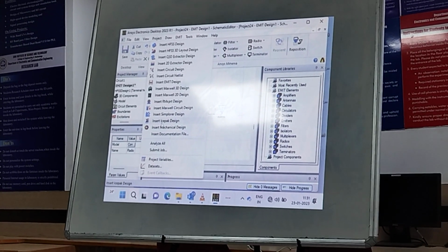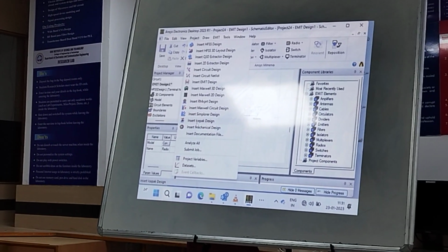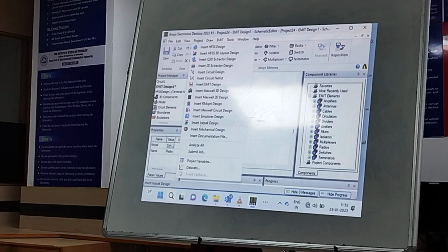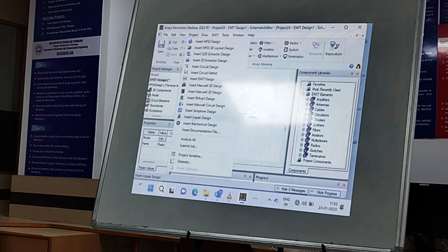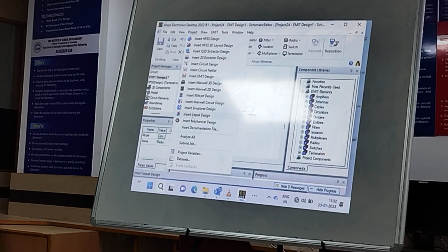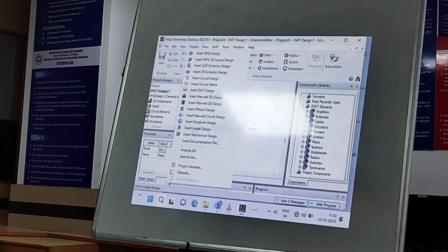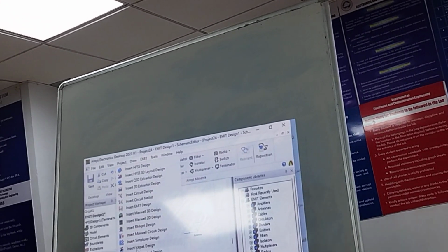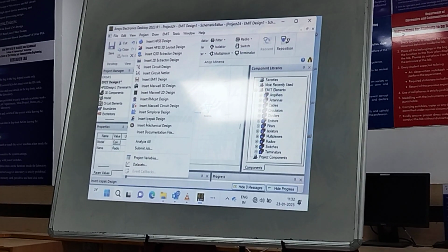And the boundary conditions, how we give it, like let's suppose in HFSS we will be giving a radiation boundary condition, or kind of PML layers we will be giving there. Okay, so instead of that kind of boundary condition, we will be giving a temperature dependent boundary condition here. Like at a particular wall, what will be the temperature, and it will be basically an external environment, how it will be, that we will be representing there, and based on that our electromagnetic signal losses will be converted into heat effect there.